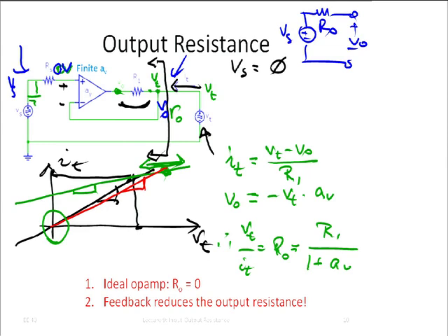Right? Okay? So anyways, then if I find that it's actually the finite gain of the operational amplifier that is the problem, then maybe I go and analyze the circuit much like we did here for finite operational amplifier gain. I look at what the error is that it causes. I look whether I can accept that error, and if not, I find some kind of modification to the circuit. Sometimes just getting an operational amplifier that has higher gain is closer to ideal, sometimes really modifying the circuit.